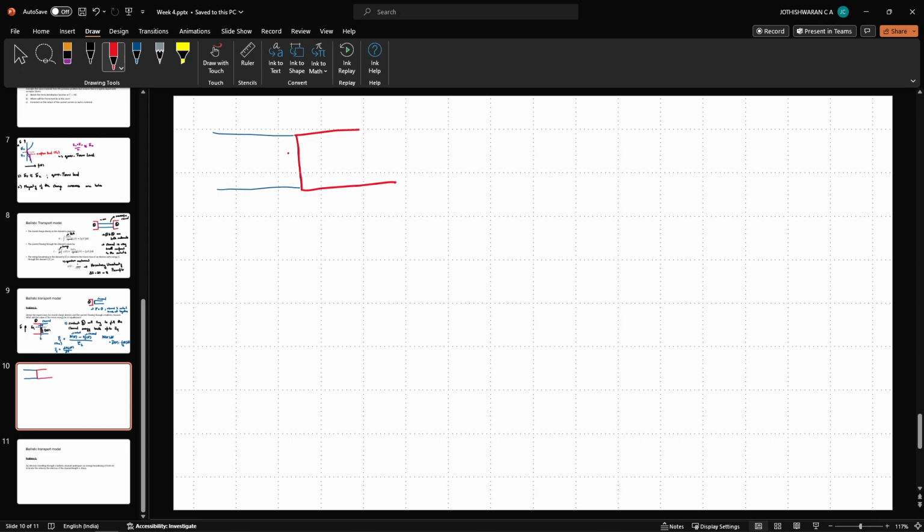Now this material is going to have a Fermi level EF2. This is contact number 2. Let me just maintain some color consistency. So this is contact number 2. And now what is contact number 2 going to do? Under normal circumstances, contact number 2 will try to fill up the system up to EF2. Now what does this mean? If there were electrons present at energy levels above EF2, contact number 2 will take them. Contact number 2 will absorb them.